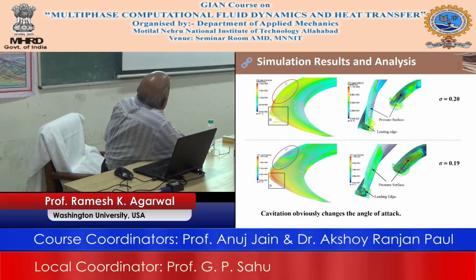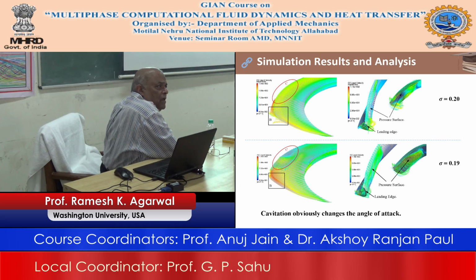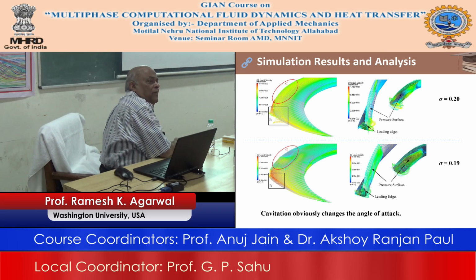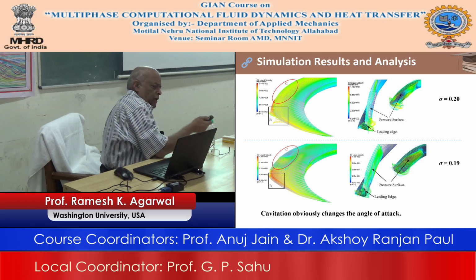You can see that the vortex is an area where the vorticity magnitude is greater than the strain. Strain is similar to vorticity. So that is the Q criterion, and it is very heavily used nowadays in characterizing regions of vorticity in three-dimensional flow. For a long time, although vorticity has existed from the beginning of fluid mechanics, tornadoes, you name it, everything has a vorticity, even a plate has a vorticity.